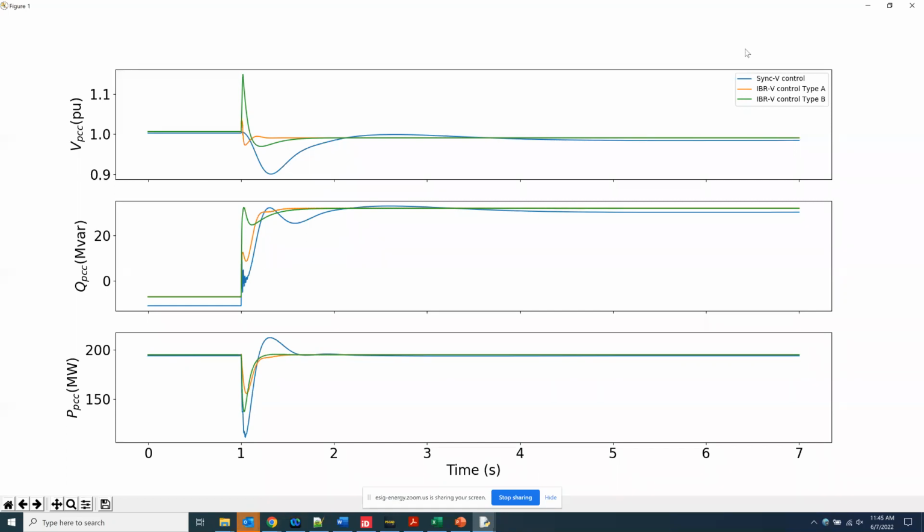One of the things here is that the types of control that do not use a phase lock loop are also not necessarily always stable under all conditions. So then it comes down to good control design across both types of control mechanisms.